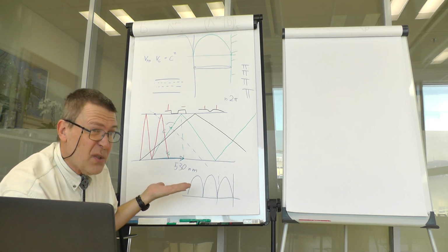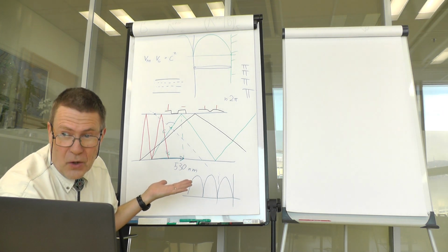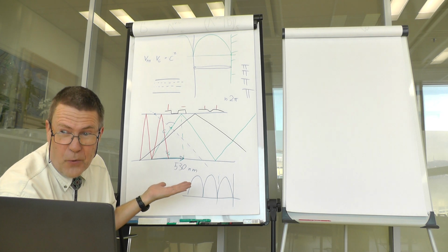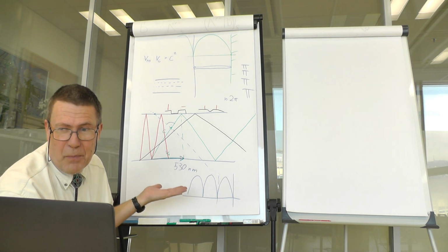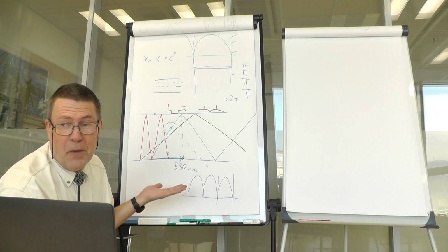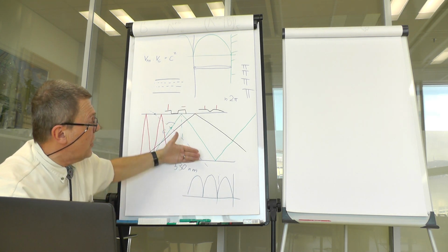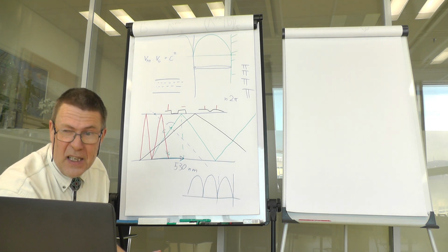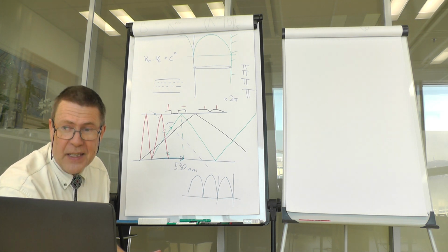As you know, most signals are not monofrequency, because a monofrequency signal carries no information. Mostly you use some kind of modulation. And the problem of such a kind of transmission line is that it's dispersive. That is, the velocity of propagation is dependent on the frequency of the signal.